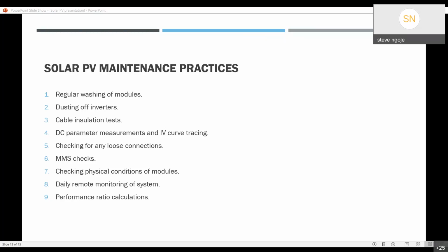After maybe you've logged for 1 week or 2 weeks, you can retrieve the data and analyze it. By analysis, you look at, for example, the peak power that was recorded, or the average power. You do data analysis in Excel or something, come up with graphs, and get the average power consumed by that facility or that client.